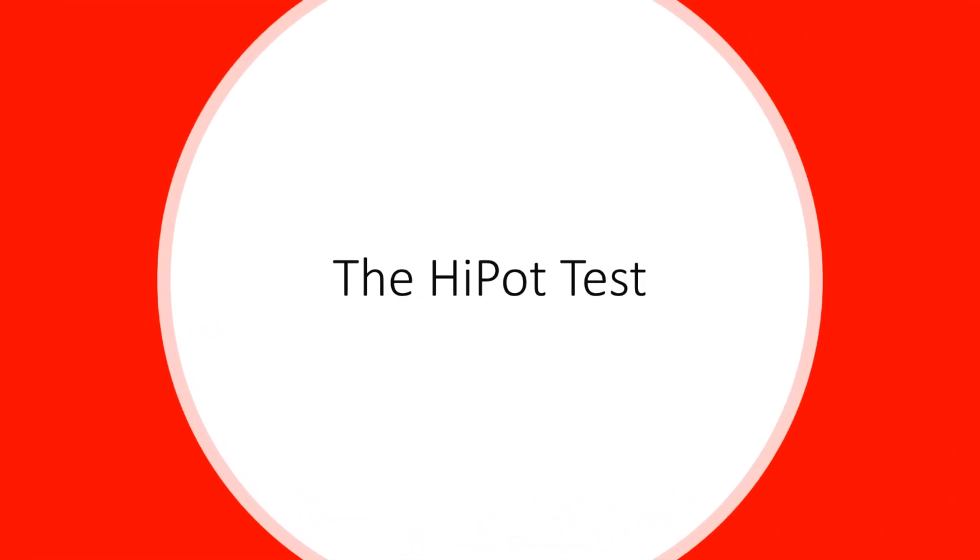Next thing we want to talk about is the actual Hipot test, which, as I mentioned earlier, is the go, no-go test when you're checking the dielectrics, and this could be plane to plane or net to net, or even net to plane for that matter. We're just doing a leakage check to make sure that the dielectrics hold up. And I'll send that back over to our AI guest for some commentary on the Hipot test.